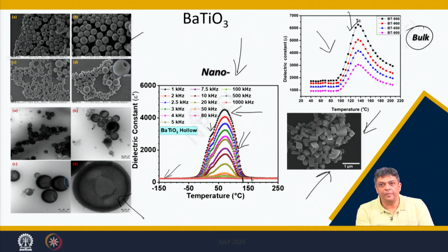But if you use the same material and you choose the dielectric as barium titanate to be operated in capacitors in the range of 100 to 150, you can see even a small change in temperature goes on changing its dielectric constant, and all your electronic calculations go on changing, and therefore the capacitance is changing, and hence the corresponding voltages which you thought you would get are going to change just as a function of slight temperature, and therefore you cannot use that kind of dielectric if you are making a capacitor which has to operate in the range of 100 to 150 or 100 to 200.